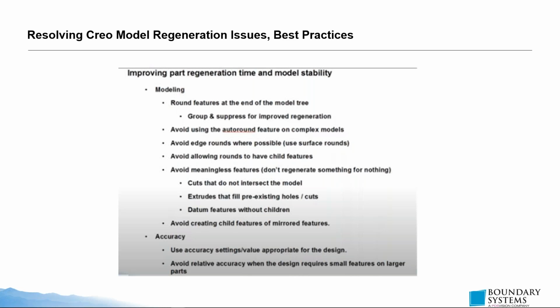It will round all the other edges that don't have specific rounds on them already. Also, avoid using edge rounds if possible. If you can use surface to surface rounds, that makes it better. Another option, instead of using just direct edge rounds, is also using an intent edge.